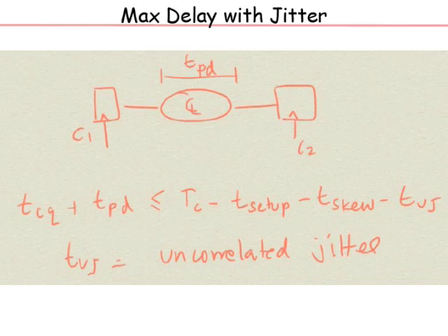And in terms of jitter, it's very difficult to design upfront. I really don't think anyone analyzes the jitter at that point. Once they have the chip and historical data, they know what kind of jitter they can expect, and with some thumb rules they come up with jitter numbers and use those for timing closure. It can happen that you are quite conservative, and people have found that sometimes the skew and jitter numbers they use are very conservative, and there is much more margin. So how to tighten that up and improve it is definitely an open area in some sense.